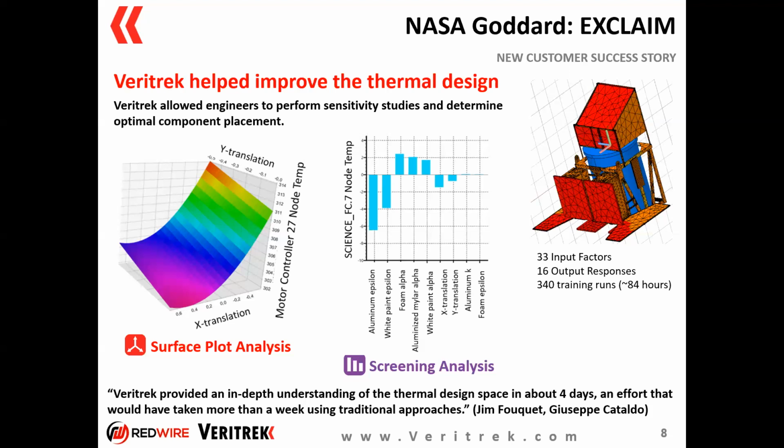A lot of that was done over a weekend. So if you set up your reduced order model in the creation tool, maybe on a Friday afternoon, click go, or use our new ROM parallelization feature, you can just let Veritrek automatically generate that training data over a weekend when your Thermal Desktop licenses aren't being used. You can certainly pause and resume your ROM creation as well. But typically, we advise folks to leverage the weekends and the off time where Thermal Desktop licenses aren't being used to generate their reduced order model.